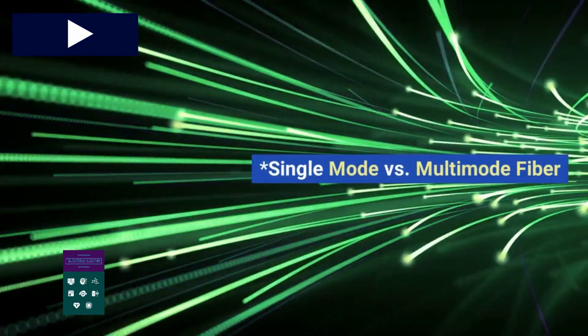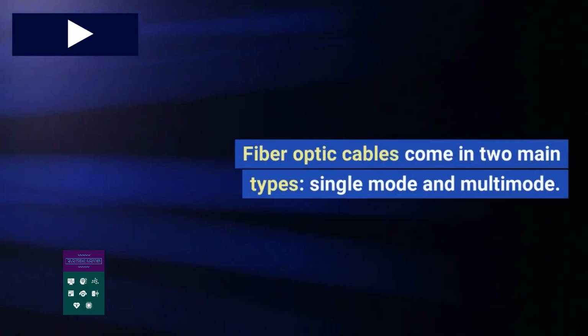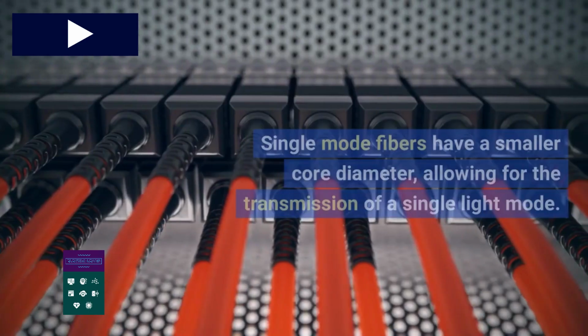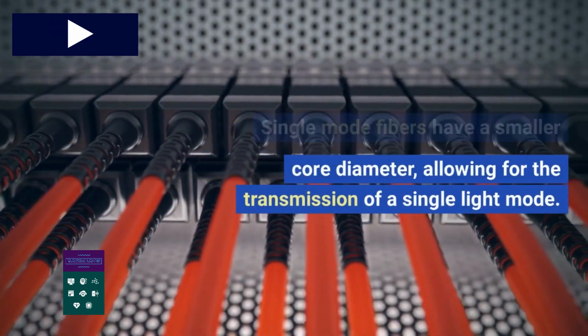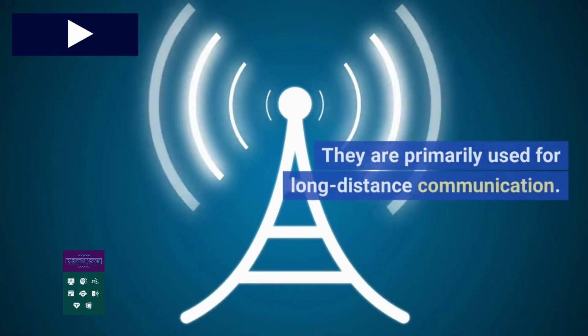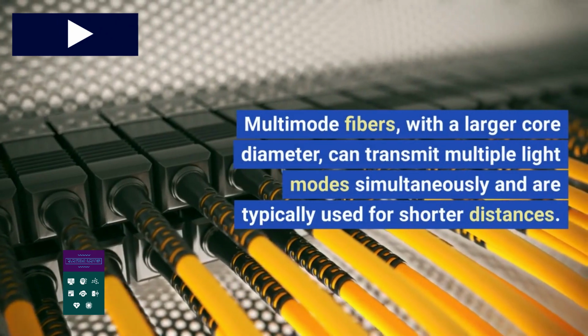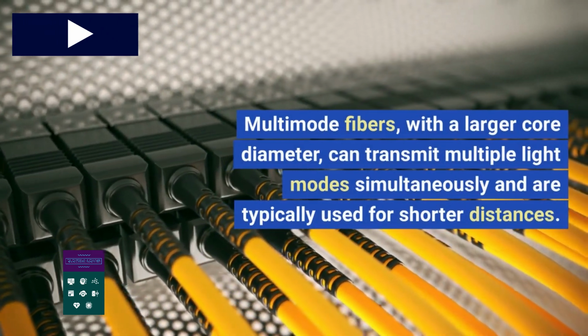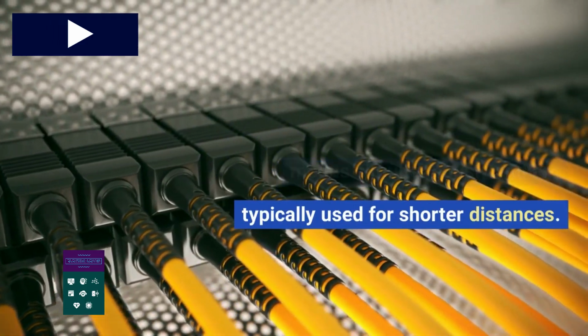Single-mode versus multi-mode fiber. Fiber optic cables come in two main types, single-mode and multi-mode. Single-mode fibers have a smaller core diameter, allowing for the transmission of a single light mode. They are primarily used for long-distance communication. Multi-mode fibers, with a larger core diameter, can transmit multiple light modes simultaneously and are typically used for shorter distances.